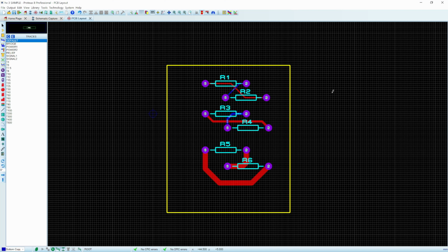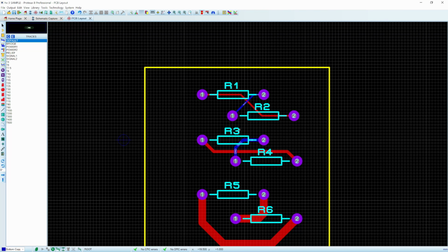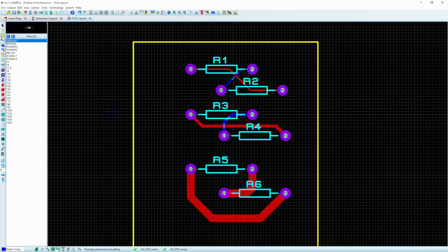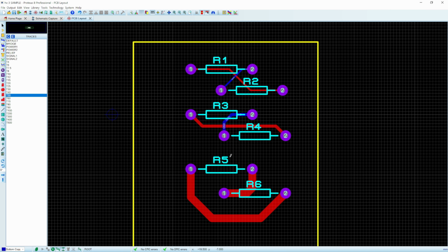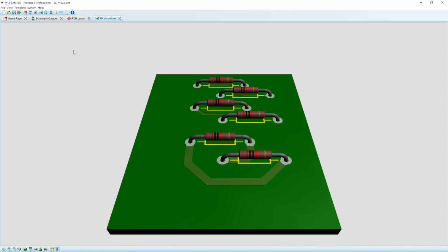And we can see that it gives us lots and lots of room around here. Okay. And we do have our three different trace widths. Okay, so here we'll try to take this guy. Okay, we can see that we can only come so close, right? We can't get through here. So this is a fantastic way for us to make sure that we have both the clearance and the trace width necessary for our design applications.